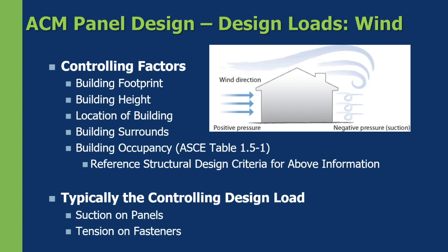There is one big one that is very important for everyone to understand, and that is the building occupancy or risk category for a building. There are four. One being the least restrictive, four being the most restrictive. So a category one risk category building you can think of as an agricultural facility. So maybe it's a barn that is storing farm equipment. If something would happen and it would fail, you have less worry about loss of life than you do a risk category 4, which would be your hospitals, your prisons, things like that.